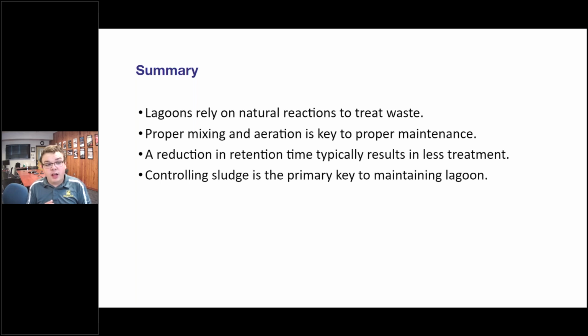Reducing your retention time is a big problem because it's going to typically result in less treatment for your solids. If your lagoon design time is already pretty high, it may not be a problem. However, less treatment is going to mean more sludge, and your sludge control is deciding how much treatment time you're getting, and that's your key point to maintain the lagoon system.